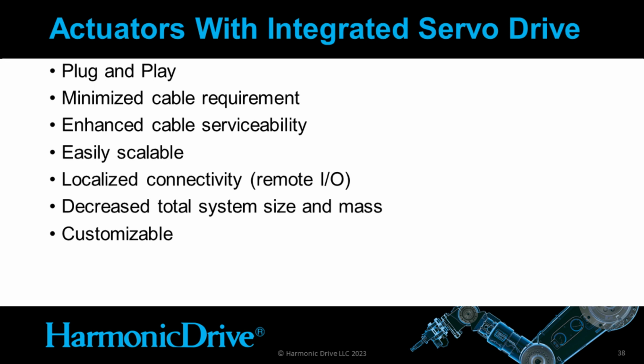Some of the benefits of integrated servo drive actuators are that they are plug and play, which means that they're modular devices. They have a minimized cabling requirement. All you need is power and communication to the servo drive. Everything else is handled. They have enhanced cable serviceability thanks to their pluggable connectors. They're easily scalable as well thanks to their minimized cable requirement and bus capabilities. They have a localized connectivity feature, also known as remote I/O. They can decrease your total system size and mass, and in some cases, they are customizable.